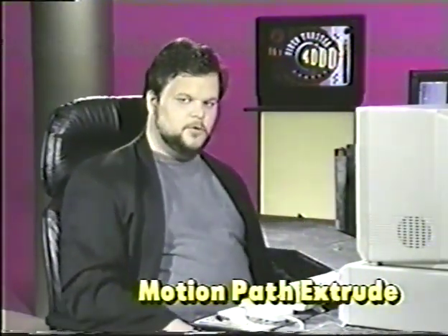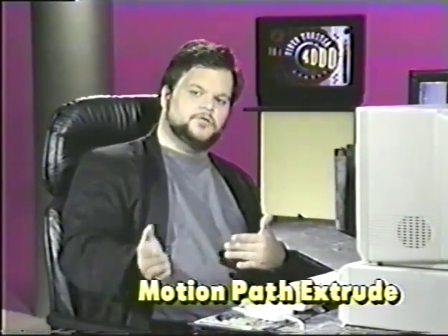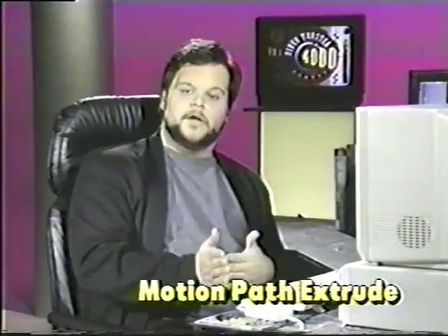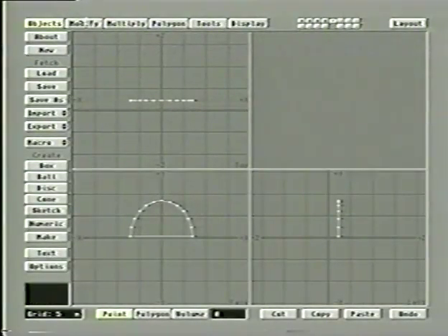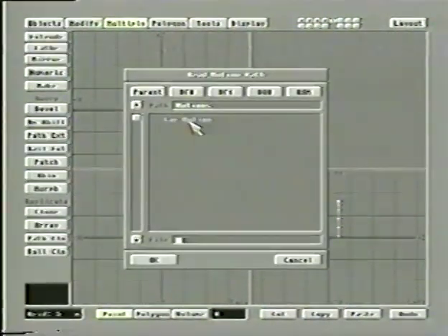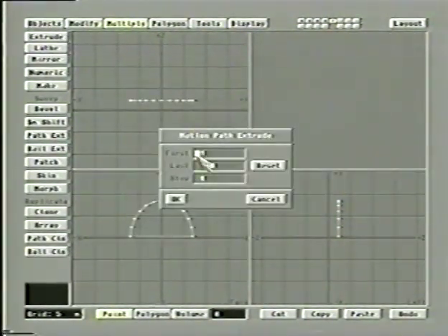We need it to follow the same path that the car is going on, though. And so to do this, we're going to use path extrude. Very, very similar to rail extrude in that it's doing an extrusion, but not necessarily straight back. With path extrude, though, it needs to pick a motion path, and it will move it along there. So let's just take our shape here. We'll go to the multiply menu, path extrude, pick a car motion,